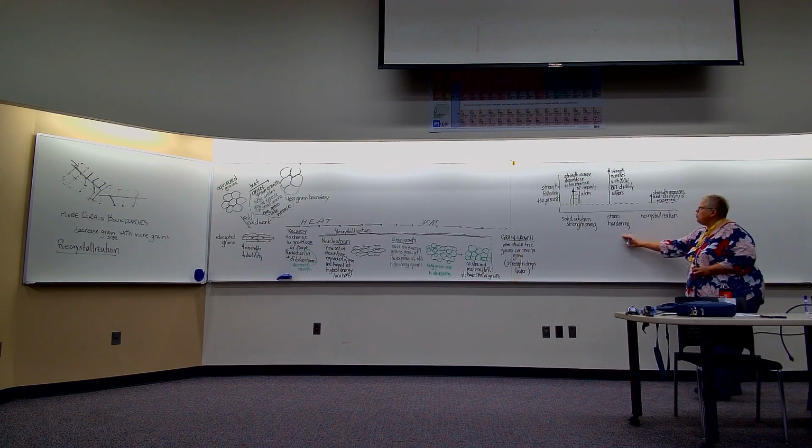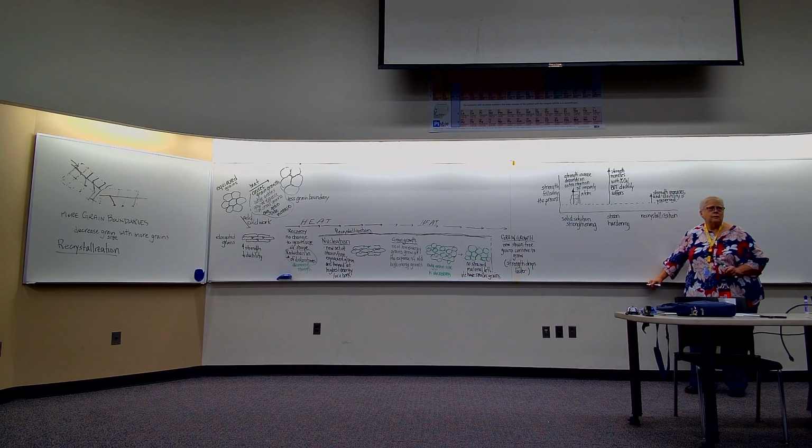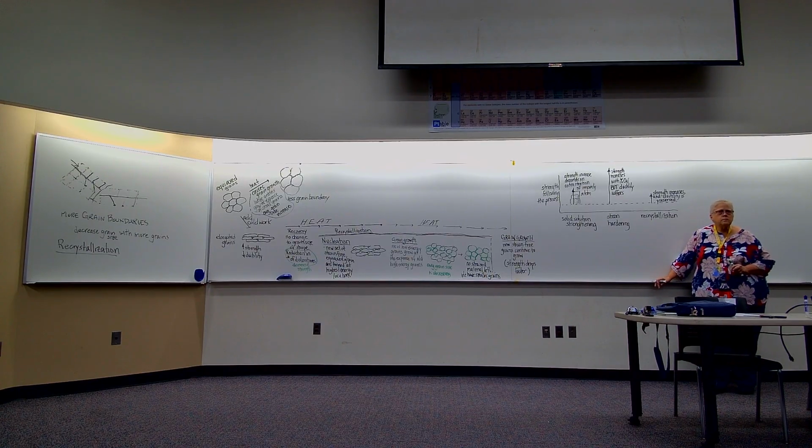When would cold work or strain hardening be the best option? When would it not matter that I'm losing ductility? Application where ductility isn't important. Better strength is really valuable. Anything in compression.